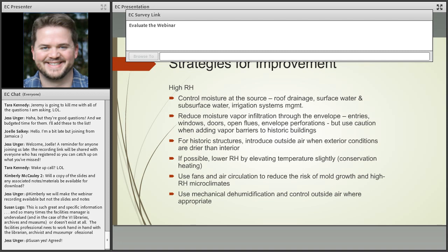It's a little bit of all of the above. The idea behind positive pressurization is that if we're pushing air out of the space that we are trying to condition, it means that the bad air, if you will, on the outside, the air that has not been cooled, that has not been dehumidified or humidified or heated, cannot get into our conditioned space. And that's the idea. We talked about this with diffusion last time and how vapor pressure and air pressure are two different things. But pressurization, when we're talking about air pressure, is all about forcing air out of our environment so that you can't let unconditioned air into the controlled space.